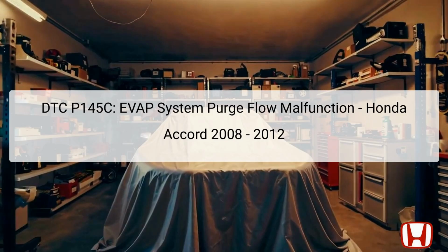The evaporative emission system is designed to prevent fuel vapors from escaping into the atmosphere from the fuel tank. The malfunction described by this code could be linked to various components within the system, notably the EVAP canister purge valve. Understanding the specific functioning features of these components is essential for effective troubleshooting.